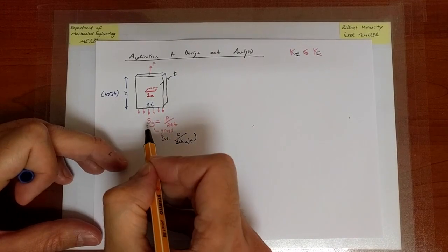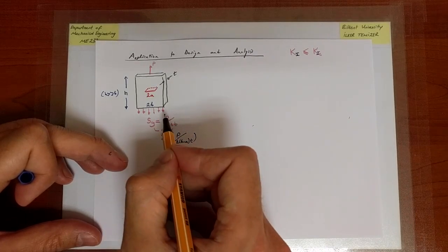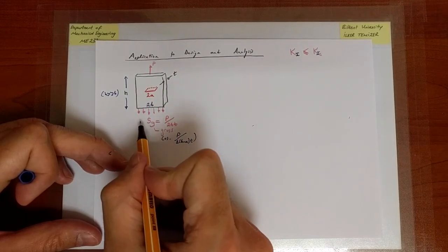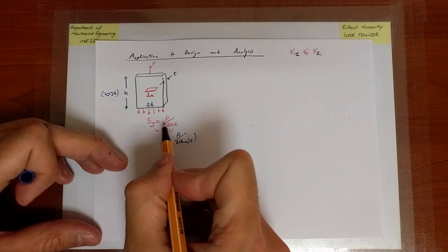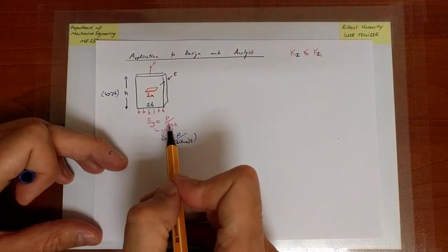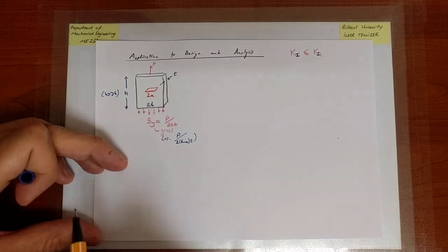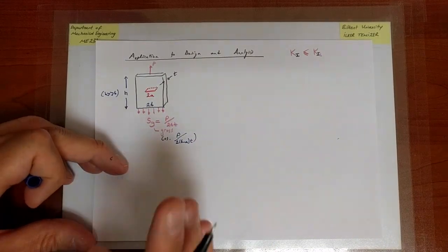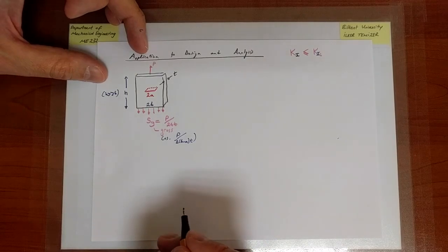But what we are going to use in our calculations is the gross stress. In other words, when we calculate the stress that is relevant to the determination of whether crack fracture occurs or not, that stress is going to come from a calculation where the area reduction due to crack is omitted. I'll come back to that once again further.